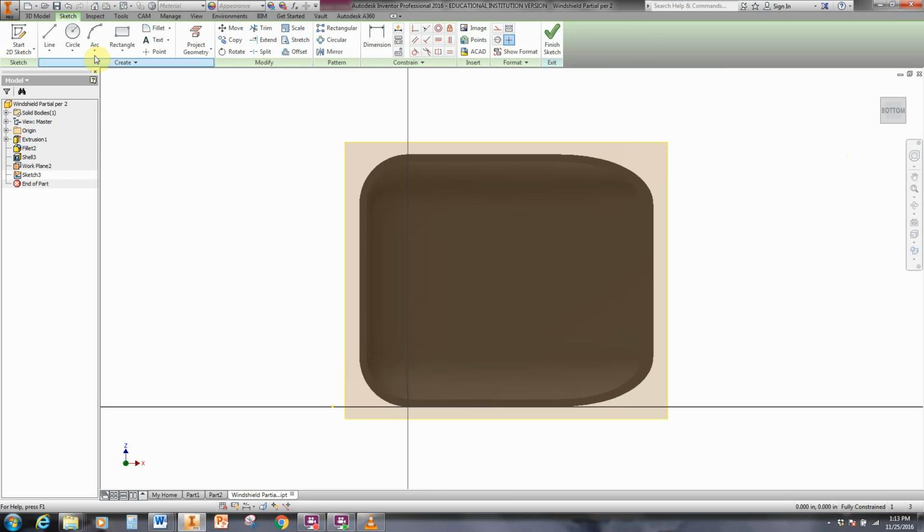So like I said, we're going to make a rectangle. So I chose rectangle, and this rectangle has dimensions of, I don't care. Seriously, we don't really care what the dimensions are yet. We will dimension it just as it is in the sketch. So we click and we draw a rectangle and we fill it in there. And I made sure that it didn't have any constraints. It didn't line up with any other dotted lines when I drew that. And I'm done with the rectangle. Hit OK. So now it's time to add some dimensions.